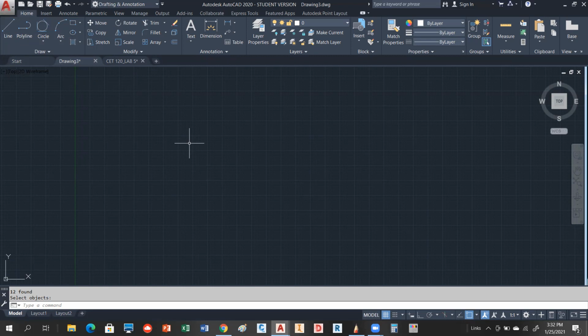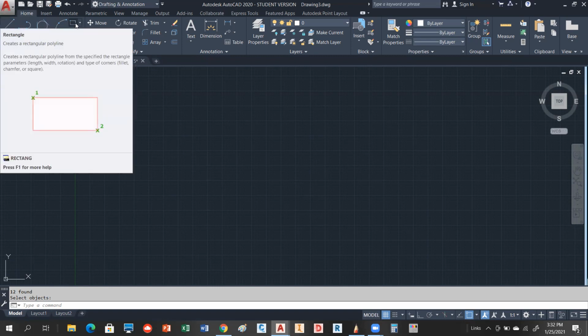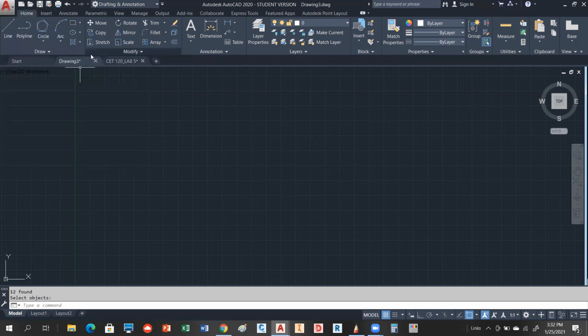And this is because this is an object called a polyline or a P-line. So we're going to look at this P-line object a little bit later, but this is a type of polyline. So this is very simple, although it does have some sub-options. When we click on this, you'll notice at the bottom there are sub-options: chamfer, elevation, fillet, thickness, and width. I'm going to show you how some of these work, and some of these things are unique to polylines, and that's why we're seeing them here.